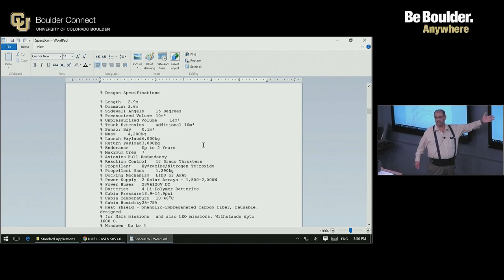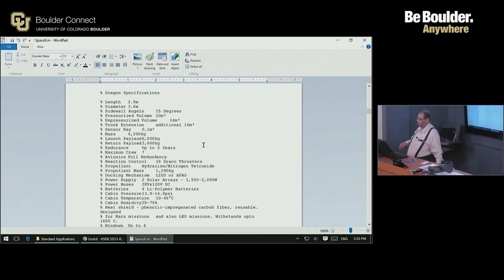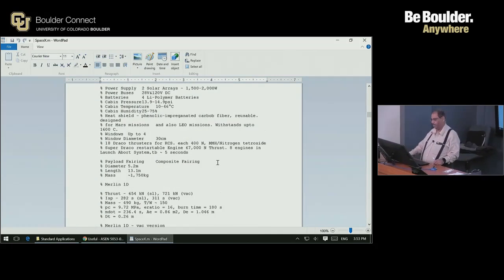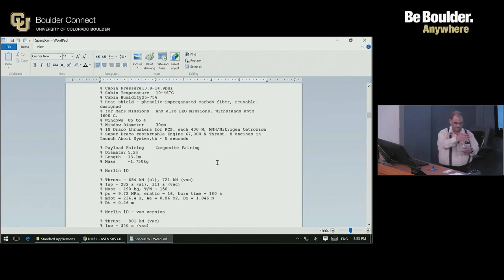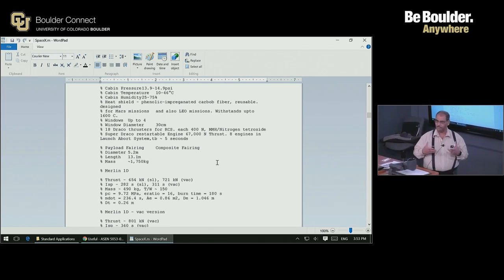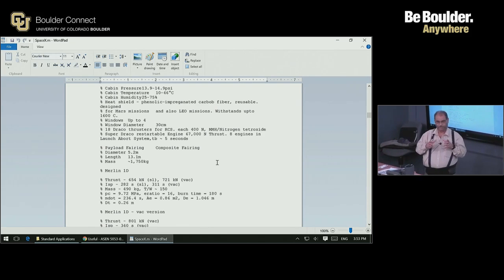There is some cargo you have to carry in pressurized volume. Others you can carry, like fuel, for example, in an unpressurized bay. Now, stages are connected structurally. For that interstage, you need to know how much the interstage mass is, because usually when you jettison the previous stage, you also jettison the interstage. And then payloads are always protected by a payload fairing.